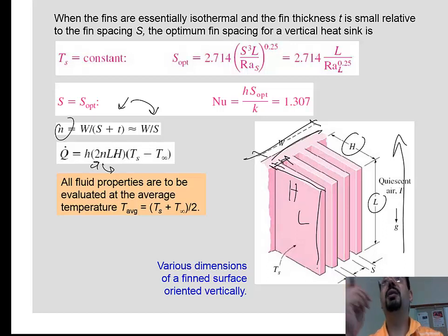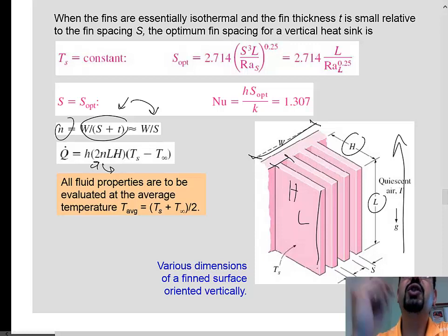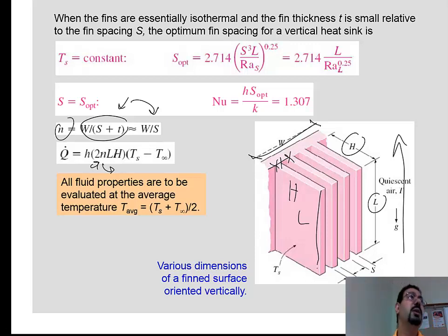Okay, cancel it. But sometimes people make the fins really thick because they are external fins. They could drop on the ground. It's not like sitting inside the laptop safe from everyone else, but rather something on the outside. Then they make them really big. And if t is really big, then we have to stick to this. What is that again? He would like to find out how many fins he has. So he would divide the whole width, W, over how much each fin occupies. The fin occupies the thickness plus the spacing. Okay? Does this make sense?